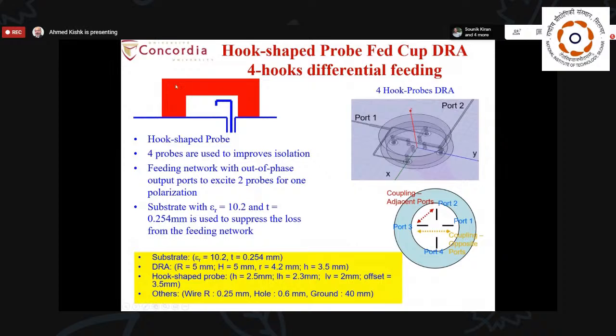And this is the other wideband element that we talked about before, but instead of L shape, we make it hook shape, because we need a lens that can pass the middle of the resonator. It will couple to another one in a differential feeding, so we bend it here to avoid that. And in this way, I can have differential feeding for each polarization.